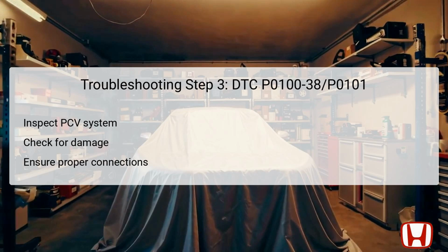The PCV system plays a crucial role in managing engine emissions and ensuring that combustion gases are appropriately ventilated. Begin by visually examining the PCV valve, PCV hose, and purge line for any cracks, breaks, or detachment that might introduce leaks or obstructions to the airflow.